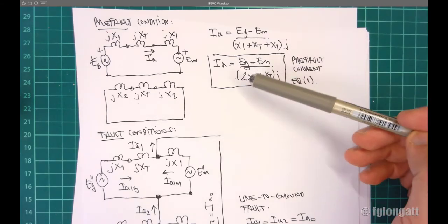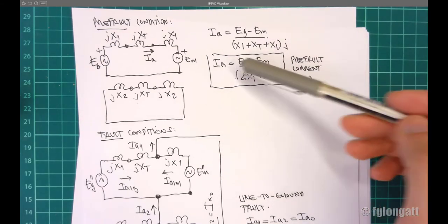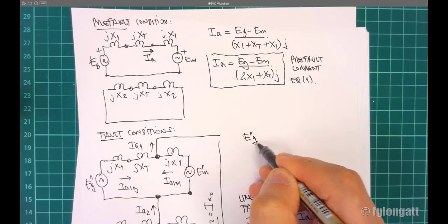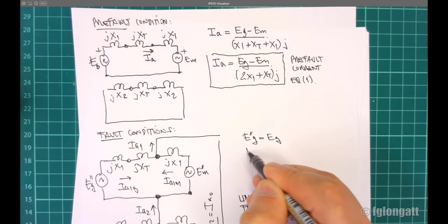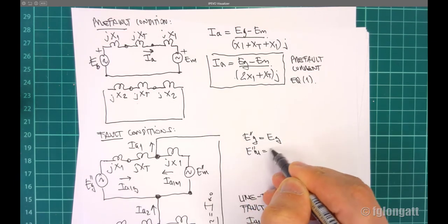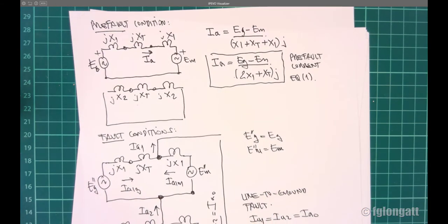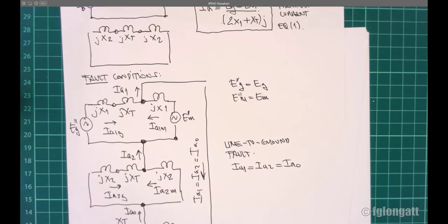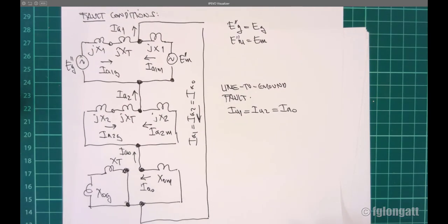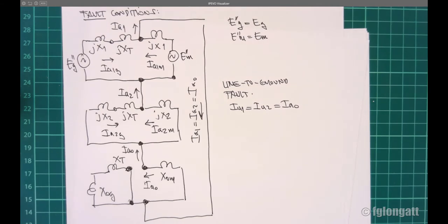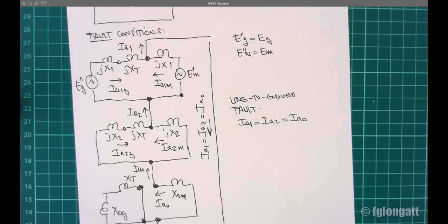but we don't know the positive sequence, we don't know the transformer, we don't know the internal voltages. There is something that we know here, that is that the subtransient voltage is equal to the steady state. And we know that because we know that those machines will not change so fast, okay? During the fault conditions, the voltages will not change so fast during the fault conditions, okay? And now what you can see over here, is the interconnection of those networks, okay? Now it's time to do some equations, okay? Let me start to write few equations over here, okay?